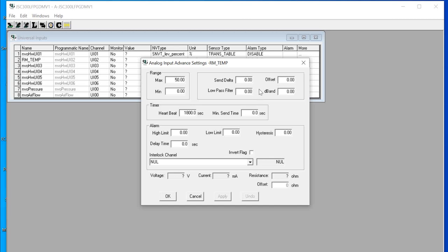Another I can mention is the low pass filter. If you sum the sensor, there is always a little bit of fluctuation. If the reading always fluctuates and cannot be stable, maybe you can put a 0.1 value. Also can think of it as sensitivity. This can smooth the reading.